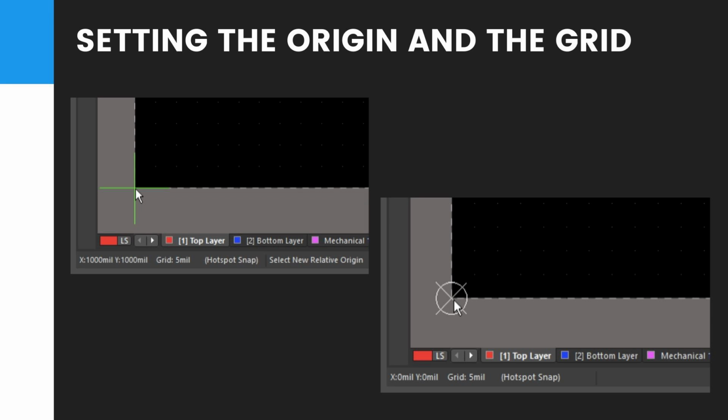For this tutorial, you will be using a metric grid. Press Ctrl Shift G to open the Snap Grid dialog and enter 5 mm, then click OK to close the dialog. Lastly, by entering the units as you entered a value, you have also instructed the software to switch to a metric grid. You can check this on the status bar.